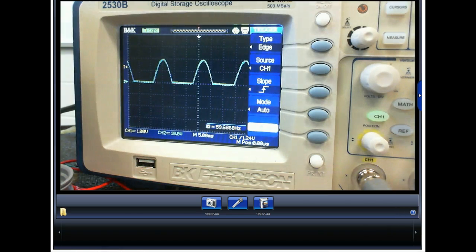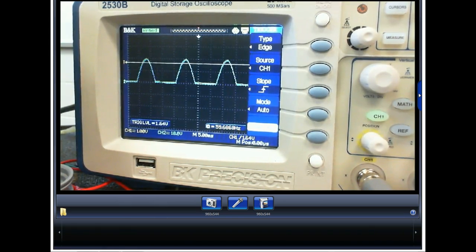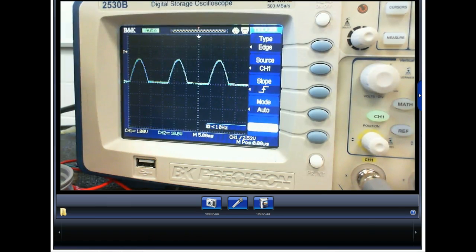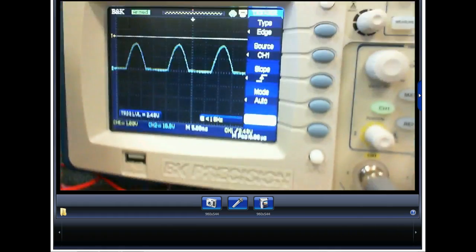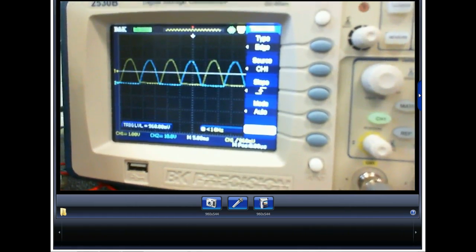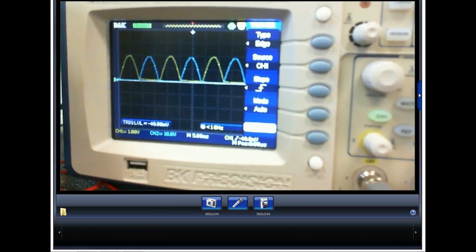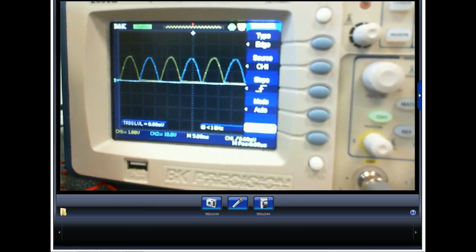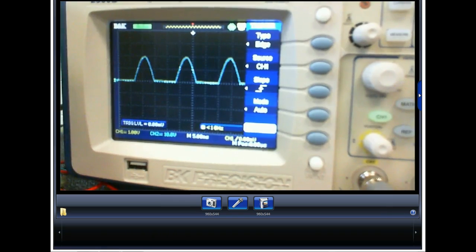So we're triggering on the rising edge, right? Triggering on the rising edge, channel 1 and edge triggered. Notice if I take the little white line and put it up here, now it never sees that voltage and the scope will go out of trigger, because the voltage is not getting that high. The edge does not get up to where I'm telling it to sync the scope. A while ago, it was down right at the 0 point, and it couldn't see the edge. That's what was going on a while ago.